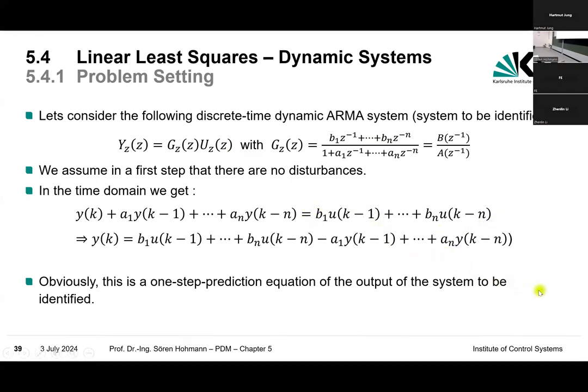That's just a back transform of the Z transform situation. Remember, z^-1, z^-2, and z^-3 just means time shift. That's the only thing you have to know here. There is nothing mysterious about it. It's data, but it's shifted one time backwards. One backwards. That's all.